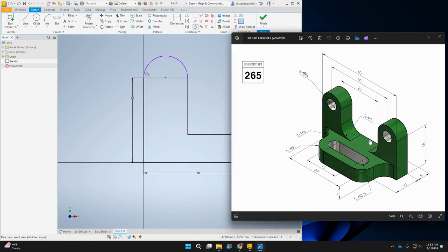So we now need to figure out how big that is. When we're looking at what's going on here, we're looking for radiuses. So I've got a 2R5 right here, which is probably these two. I've got a 2 diameter of 5. That's the holes in the middle. 2R5, so that's those two. 2R6 here. Okay, 2R2.5. That's in the slot. And I don't have any other radiuses around here.